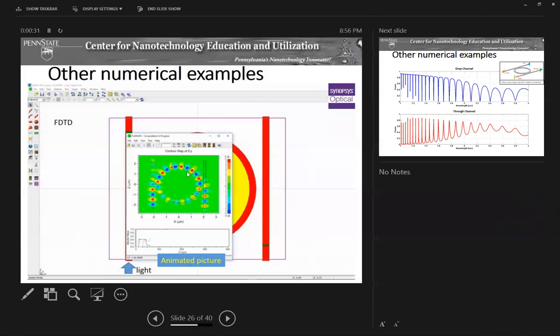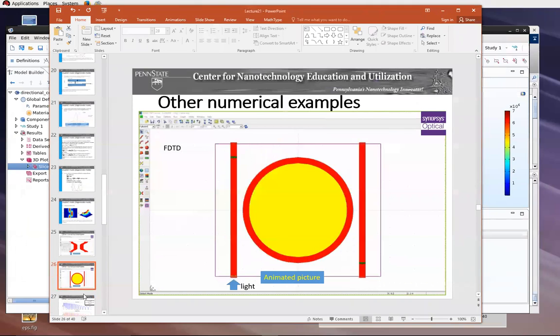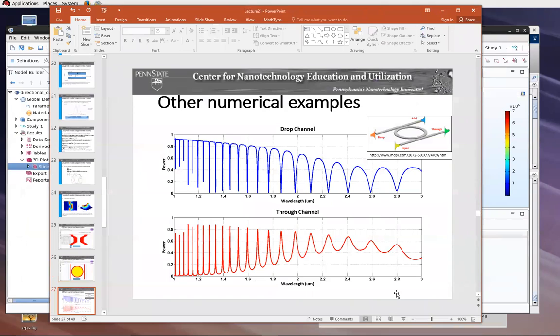Yeah. So we're going to look at the two time monitors results here and there. Okay. So these are called add-drop filters, basically. So you put the beam from one port, and as a result, you have three possibilities, right? So this ring resonator will be resonating for certain wavelengths, and it will just couple the light very similarly like the couplers that we investigated to the other side, right?